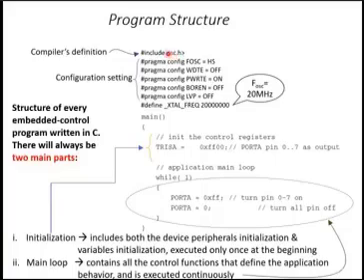This is where you put your compiler definition. So when you are working with PIC 16F, the compiler header must be xc.h. If you are using a different model, you need to put a different compiler. But right now for PIC 16F, it is xc.h.